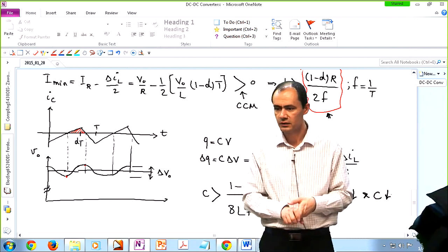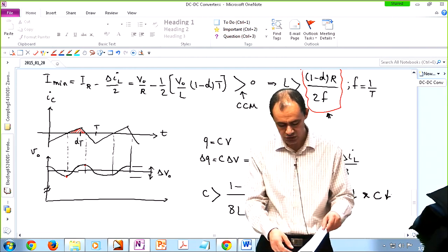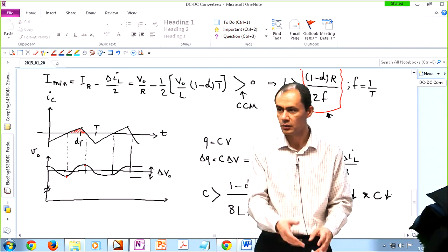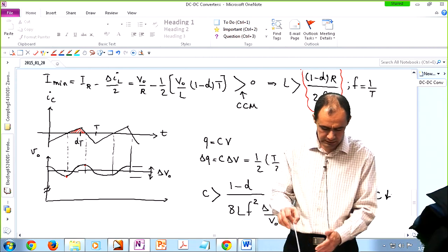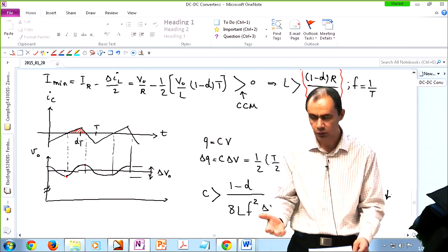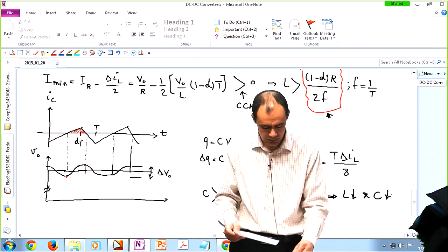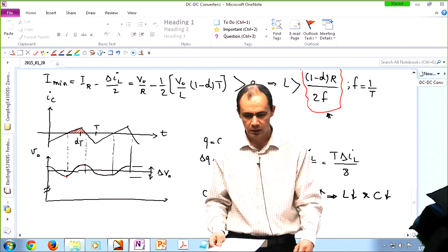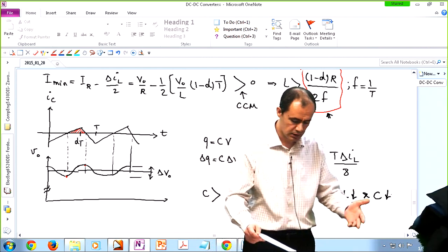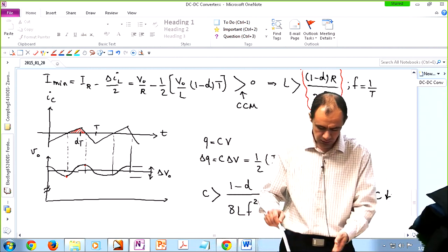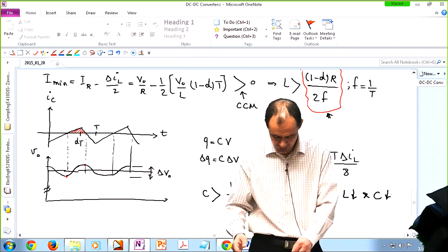So in a cell phone, for instance a smartphone, the switching frequency of those buck converters is actually relatively high, like 10 megahertz or maybe 5 megahertz. But for a classic DC-DC converter that you use in a non-portable application, processing, for instance, 1 kilowatt, your switching frequency is maybe about 100 kilohertz, okay? If you're using IGBTs, and we are going to introduce IGBTs later, then the switching frequency should be a little lower because IGBTs are not as fast as MOSFETs.